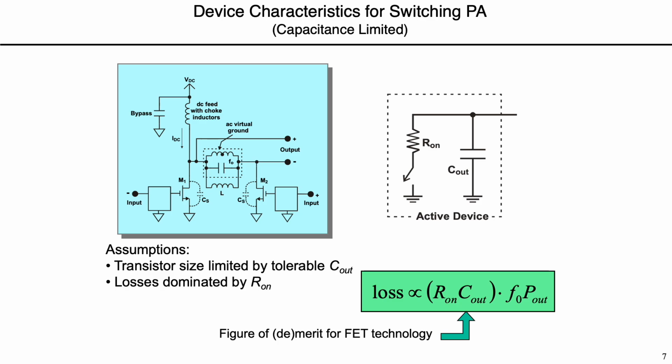So if you look at this, if you scale the transistor up, basically meaning you take the transistor and take another copy of it and put it node for node in parallel, what would you do to these parameters? R on would be half, right?